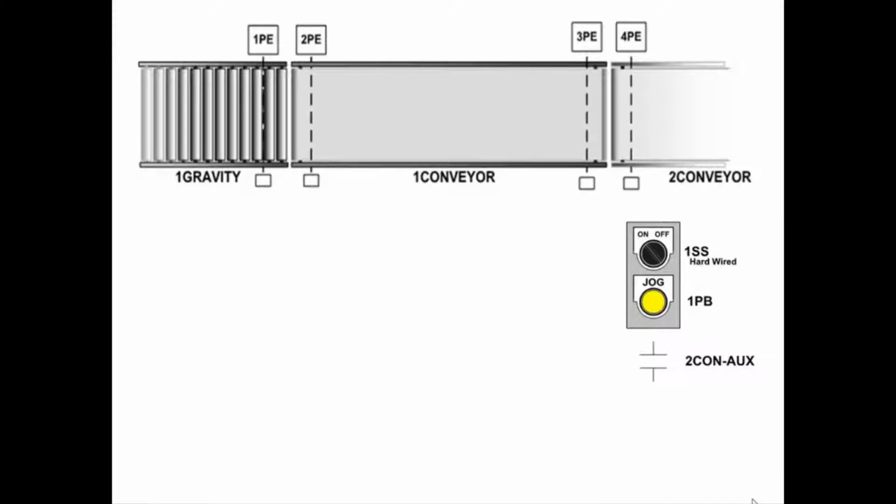And then if 2 conveyor shuts down, but cartons are still being unloaded from the truck onto the gravity conveyor, we can stack them up on one conveyor. There's 2 ways of looking at it. One conveyor can either buffer unloading the truck, or it can buffer cartons when 2 conveyor's not calling for cartons. And it may sound the same, but it's not.